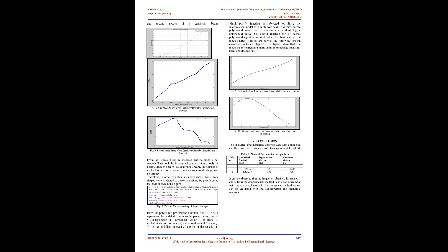The time domain acceleration data thus collected from the accelerometer is passed to the DAQ module where signal conditioning occurs. This conditioned signal is analyzed in LabVIEW software. In LabVIEW the type of input is selected as acceleration. A while loop is created and inside this while loop a DAQ Assistant block, which represents the DAQ module, is taken.